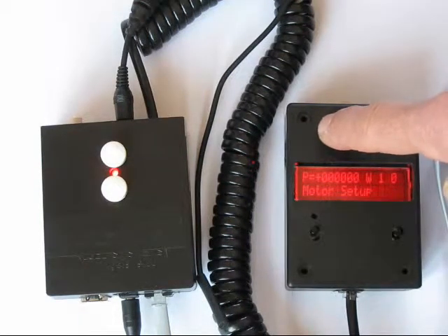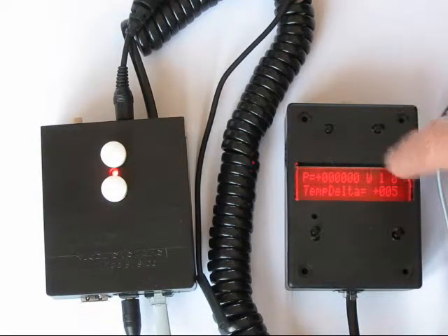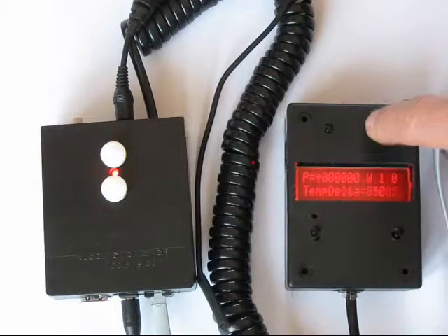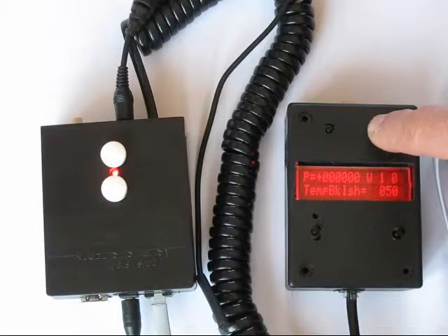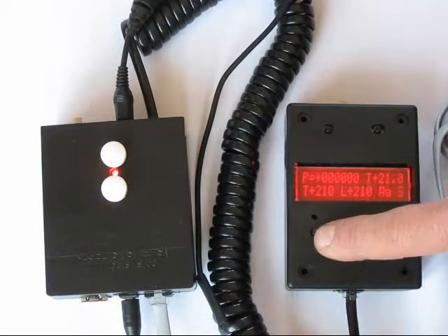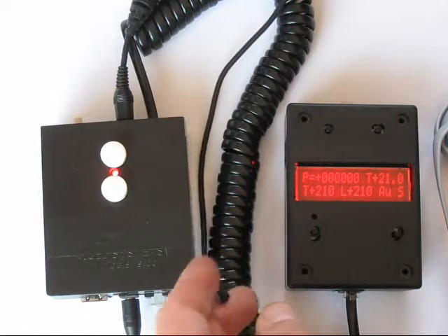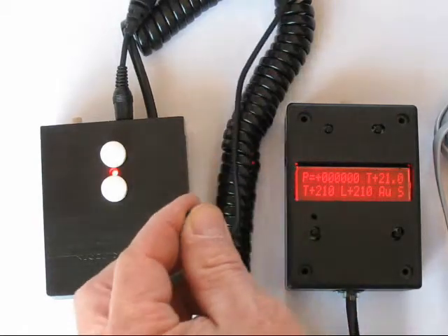So let's go watch some temperature stuff now. Every half a degree C, we're going to move 50 steps, and we're going to account for backlash if we reverse direction by 50 steps, and we're going to go into auto mode. So right now the temperature is 21°C. This is a little temperature probe hanging off the unit right here. Okay, so I'm going to just squeeze this.